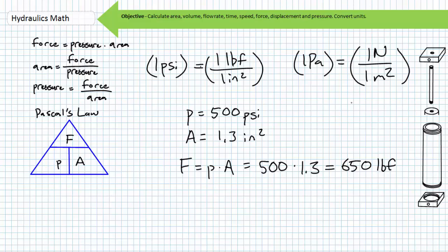This means that areas expressed in square centimeters do not directly convert to force when multiplied by pressure, since pressure is measured using a square meter standard. This necessitates an annoying but necessary conversion. 1 square meter is equivalent to 10,000 square centimeters.